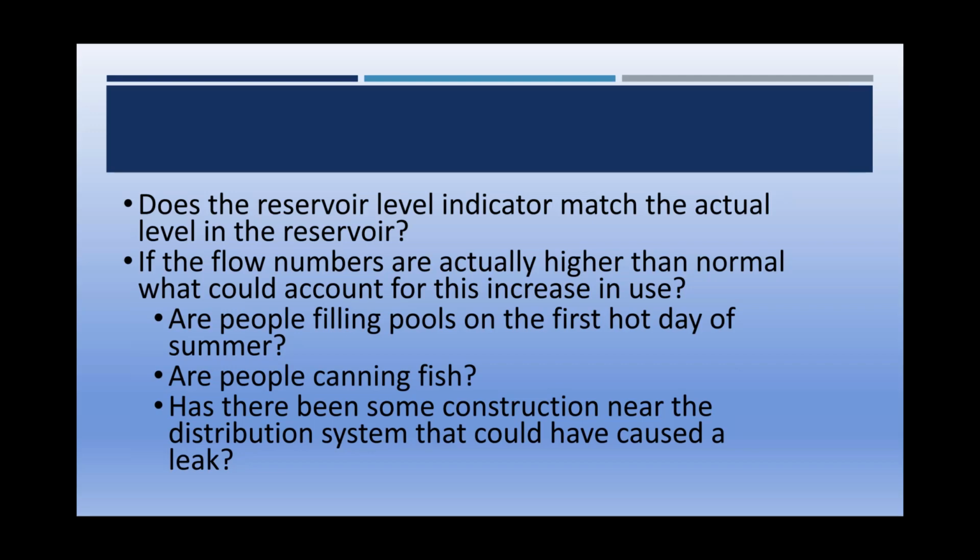But what it meant was that the gap in that pipe was narrowed down to about half of what it should have been. That's why we didn't get the dynamic pressure coming out that we really should have had, given the size of the pipe. What our problem was when we ran swabs through the system, and swabs in this case are basically big sponges that we just push through to try and scrape the sludge off the walls of the pipe, they had to be forced through that gap, and that was enough extra force on that line to pop it out of the pipe in front of it, caused a big leak.